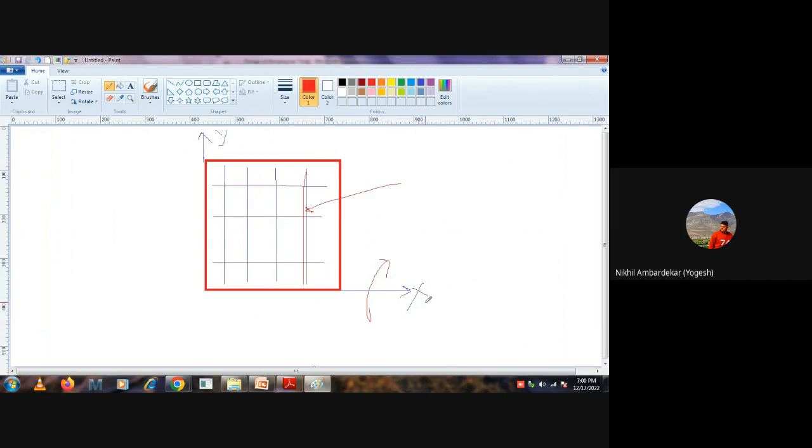So my answer was not correct. Got it? If I want to find the vertical reinforcement, I need to find the moment along x-axis, because the wall will bend in this direction, correct?